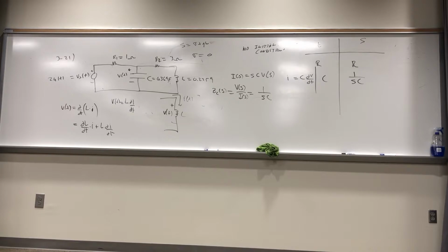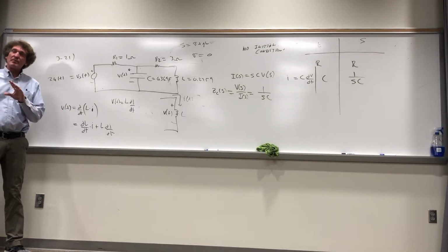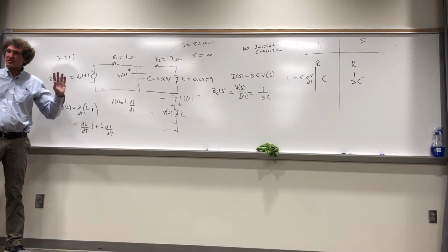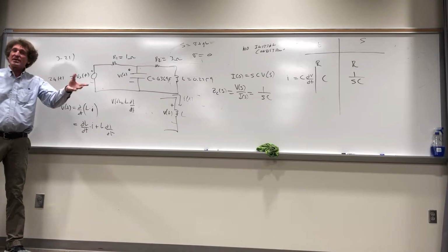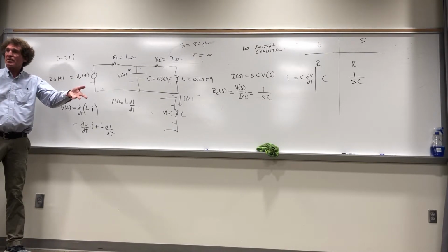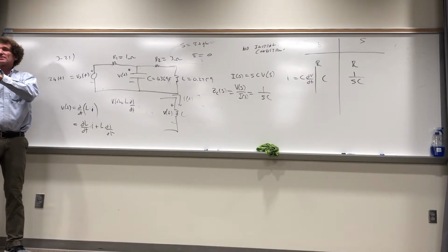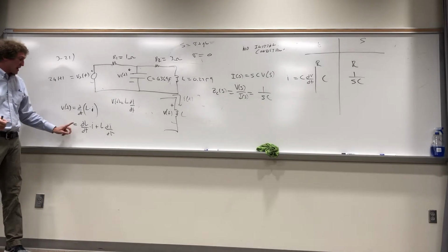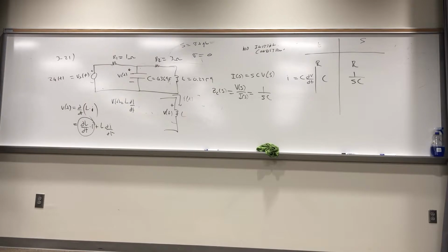Well, if they want a really large voltage so that no matter how far apart you spread the switch it'll keep arcing, what they'll do, and I've been at Eglin Air Force Base when we've done these kind of things, is get a large inductor and put a lot of current through it. Remember, their goal here is to generate a ginormous voltage. As they open the circuit, they'll blow up the inductor simultaneously. In the process of the thing blowing up, the inductance is changing rapidly, and this term overwhelms the voltage, and it becomes ginormous. That's the term I use.